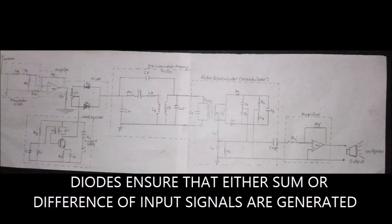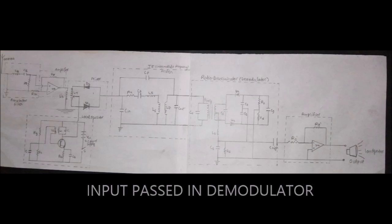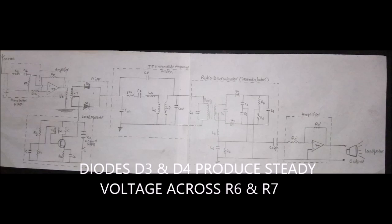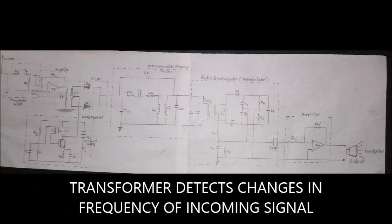In the mixer, the diodes used ensure that either the sum of the two input signals or the difference of the two input signals is generated. The IF filter is just another RLC band pass filter. Next, the input is passed into the demodulator where the diodes D3 and D4 produce a steady voltage across R6 and R7, and hence the capacitor C9 charges up. The transformer enables the circuit to detect the changes in frequency of the incoming signal.